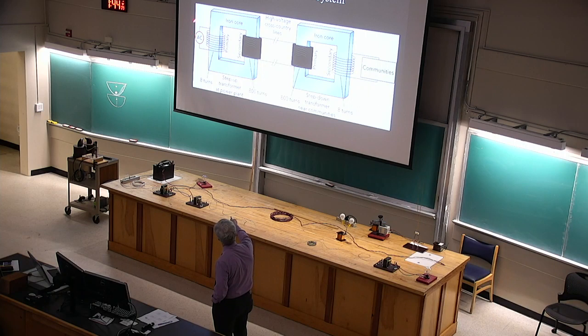There's the generating circuit where they produce the alternating current. There's the transmission circuit, which is electrically insulated from the other circuits, but carries a smaller current of electric charges, each packed full of energy, and therefore at high voltage. So these cross-country circuits are, in effect, very high voltage circuits.